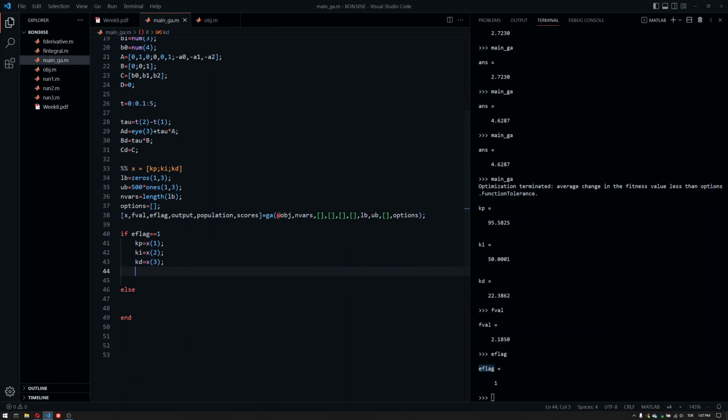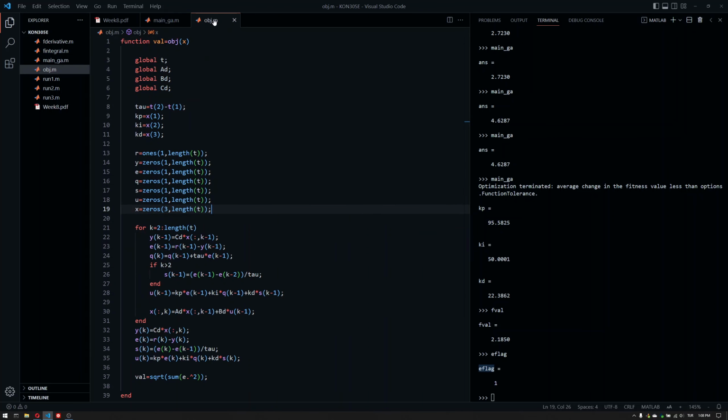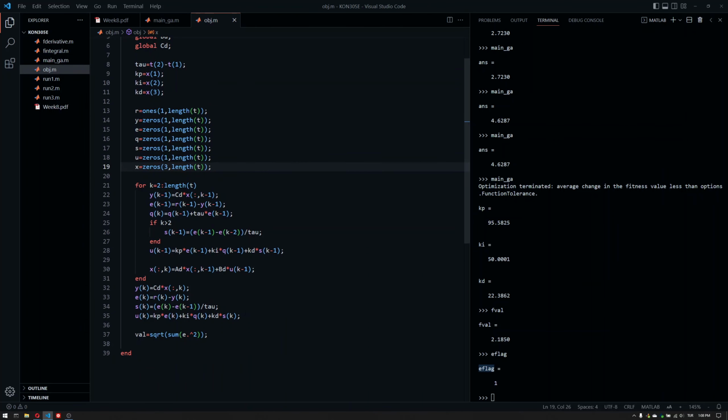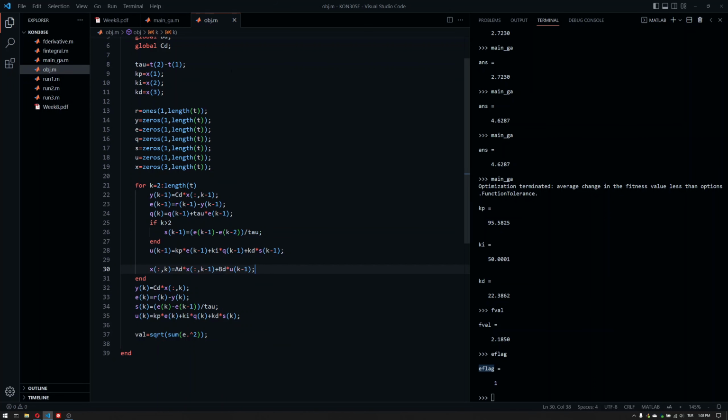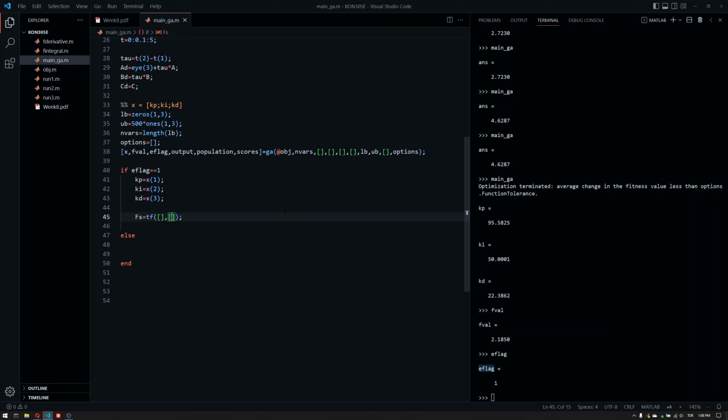I'm not going to again use my zero-order-hold methods to not overcomplicate it here. But basically, I'm just going to use the Control System Toolbox because I can. What you can do is maybe separate the simulation from the objective function. Because we have everything available here, we can have another function and call that function inside of this function, and it will just return the objective value, whereas when I call it externally, I can just simulate it with the same code. That's also possible, but this video is long on its own, and it's complicated. I'm not going to bother with that.